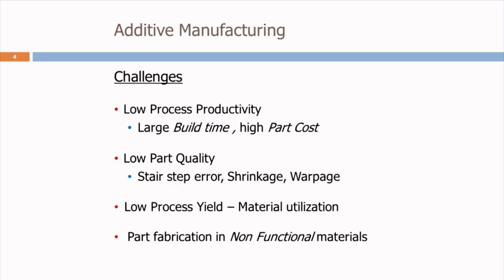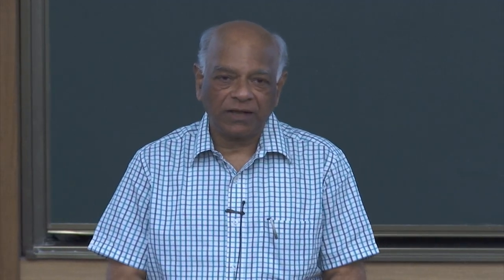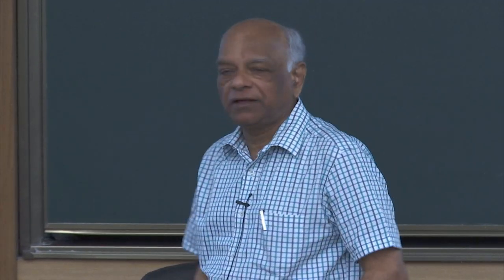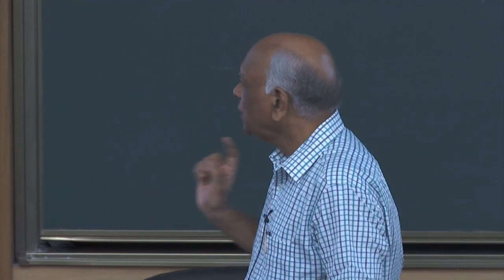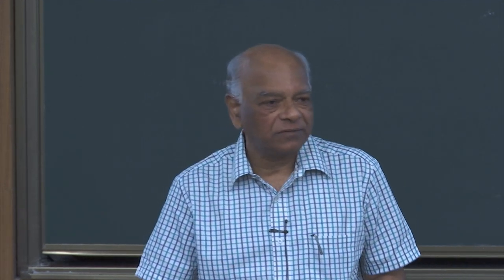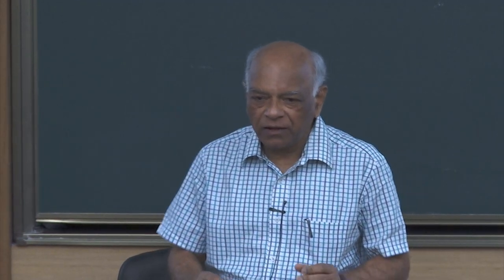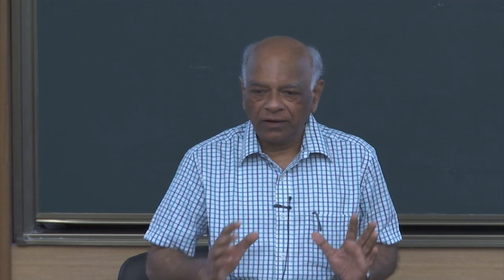Though we find that additive manufacturing is a very good process which has significantly cut down the time from the product to the kick-off stage, or what we term as the product development cycle time, it has several basic limitations which actually form the challenges for this particular technology. First and foremost, it has very low productivity. It has a very large build time, primarily because the component is built layer by layer, and that makes the part cost very high.